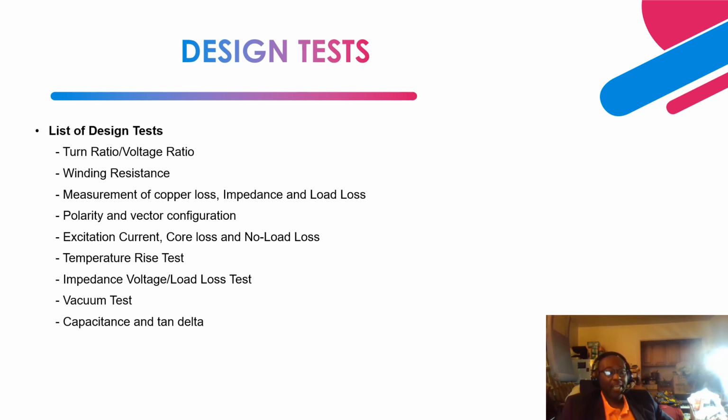For a service age of more than 10 years, it should not be more than 10%. Anything greater than 10% is a concern for us to investigate and perform other testing, like impedance testing and SFRA testing, to identify the need to perform an internal inspection of the active component of the transformer.